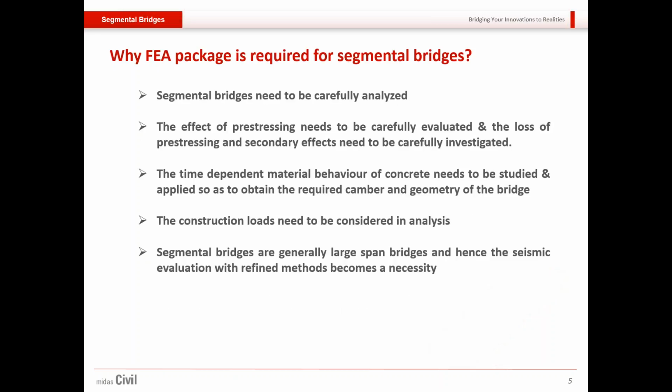Okay, so we'll begin with why an FEA package is needed. So segmental bridges basically need to be carefully analyzed. Any such project would involve a huge sum of money, and any error or misjudgment in such kind of projects would be very costly in terms of money as well as life. So FEA, being one of the most precise solutions out there, needs to be adopted for such segmental bridges. Then the effect of pre-stressing needs to be carefully studied for this kind of indeterminate structure. Yes, of course, manual calculation is possible, but it would be very time consuming and the chances of error would increase.